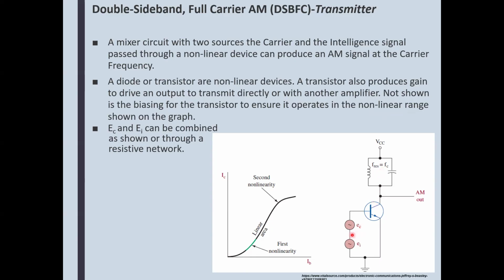So once we have that carrier frequency here, and it goes into the input of this amplifier, the transistor amplification device, let's call it an amplifier, then the tank circuit, if it's tuned to that carrier frequency, is going to resonate with the carrier, so the signal is going to skyrocket. It's going to go stronger.